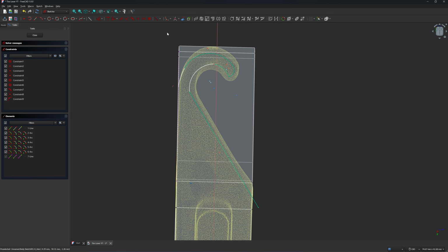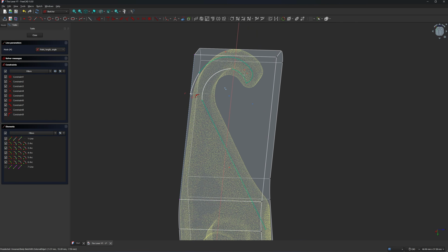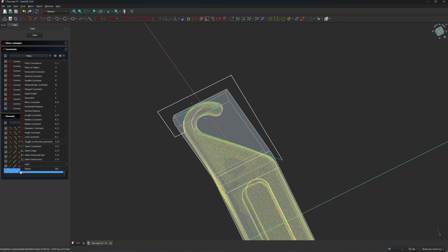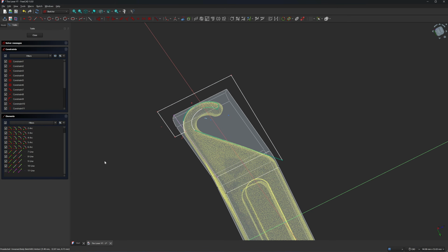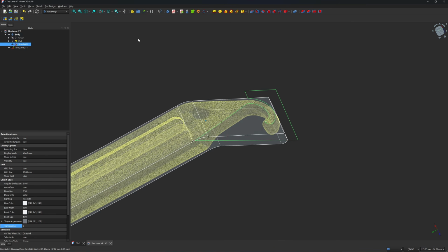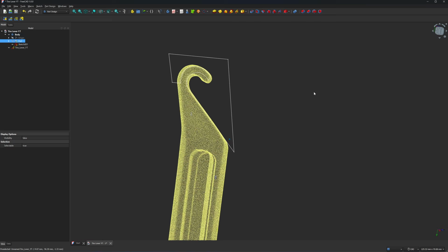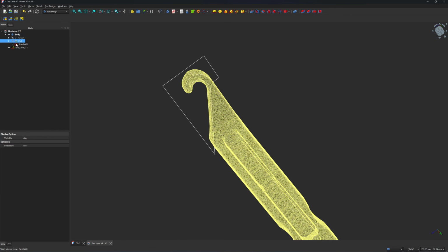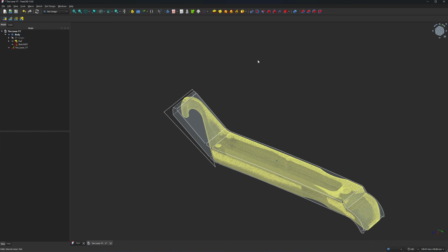This will be the cutting profile of the first sketch, so everything in this profile will be cut. I will remove this projected line. So we have 11 lines in this sketch. So the next sketch that we are going to use for the loft cut has to contain exactly 11 lines. Let me close it. Let's turn off the pad. Here's the first sketch that we use for cutting. Okay, let me turn this part on.